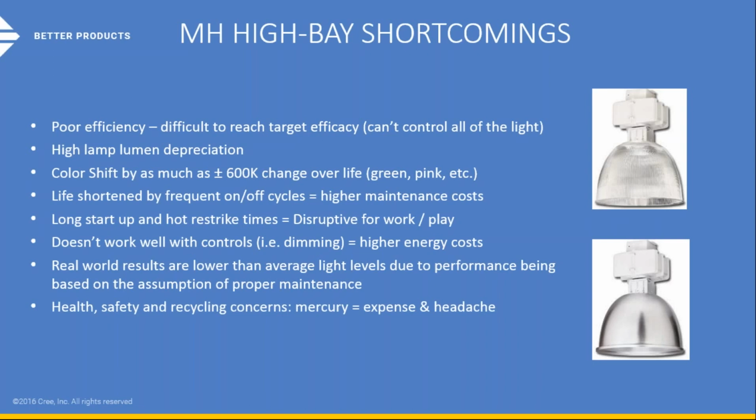And I think lastly, what it's showing here is health and safety. So think about the kind of products that you're using. There's mercury content in metal halide bulbs, and also from a disposal standpoint, if you have to actually throw these products away, you're required to do it in a special fashion. You might have to have special containers. You certainly have to deliver them to a special facility to actually consume the mercury products. So that could add to the cost and the overall maintenance of your environments.